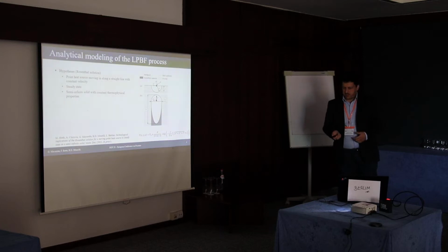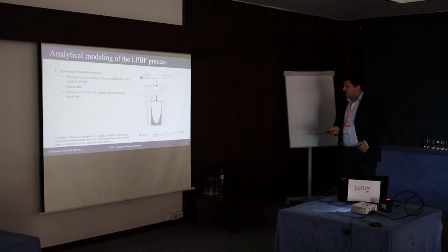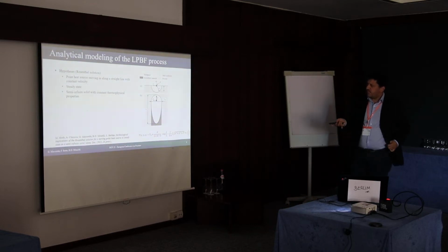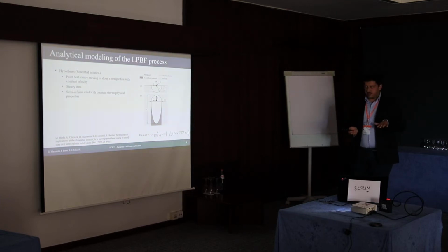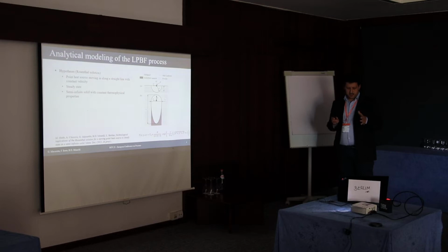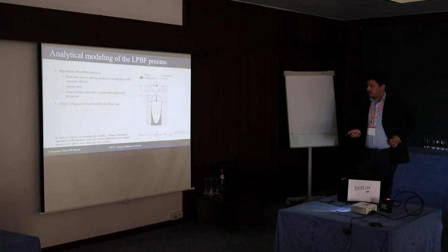Here I just provide an overview. We'll explain it better in a dedicated paper, as here we have no time. This model works with a point source moving along a straight line, steady state, in a semi-infinite solid, so it works properly for the hatching part of the specimen, not for the contour part. It's something on the boundary.